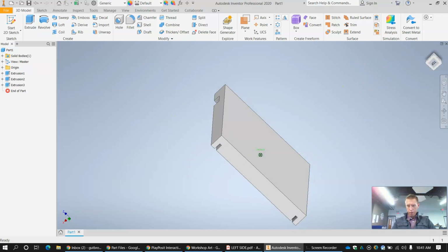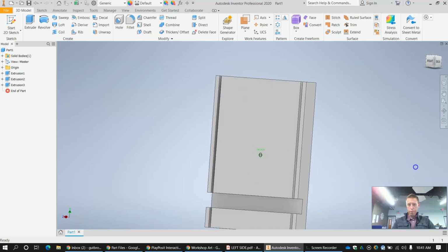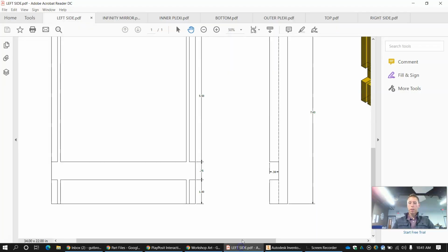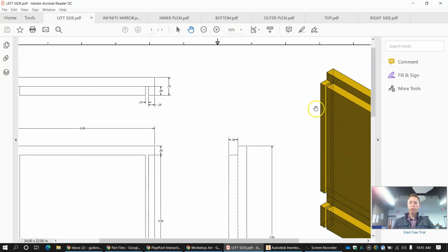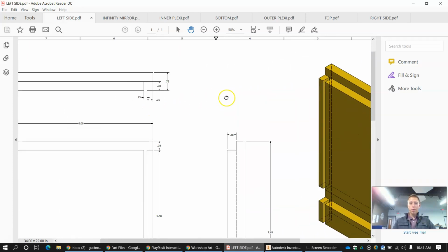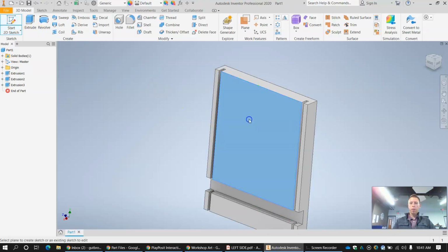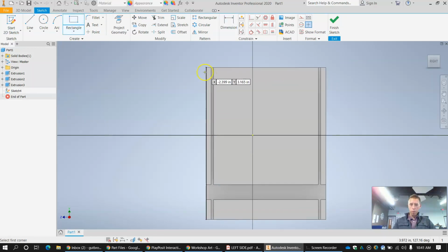And then again, I'm going to be really proud of myself for my efforts. It is halfway through. So far it's correct. Last thing to do. It's got that cutout at the top. If you look here, we just have that cutout. So basically we're doing the same thing we've been doing. We're just going to do a rectangle and cut this top shape out. That shape is halfway through the wood, 0.375. It's 0.375 tall, and it's directly aligned with the top. 2D sketch on the surface, rectangle tool. Line it up in the corner, draw my rectangle.